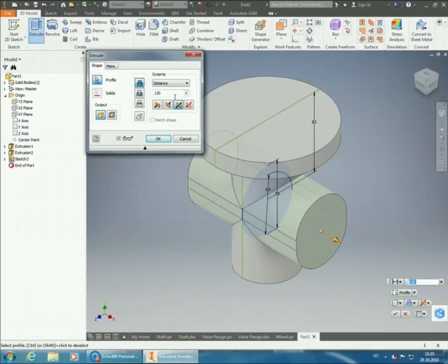And the total width that we're supposed to have here is 200 millimeters, but that's including the flanges that are supposed to be on the ends there. So we're going to subtract the thickness of those flanges. So 200 minus 19 minus 19. Then we get the total width of this section of the valve.